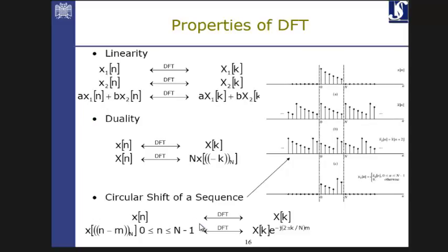Let's talk about some properties of the DFT transform. Again, DFT transform is a linear transform. So all the kinds of transforms we explained in the course and many other courses are all linear transforms. So they have the properties of linearity. So the superposition property, you already know that. It's clear, summation of the signals and scaling them, it just happens in the output.